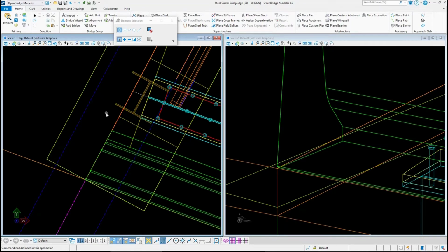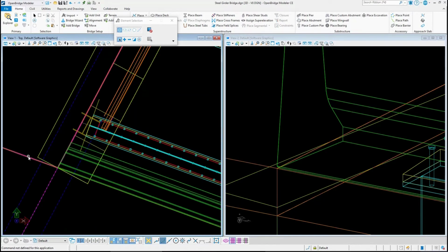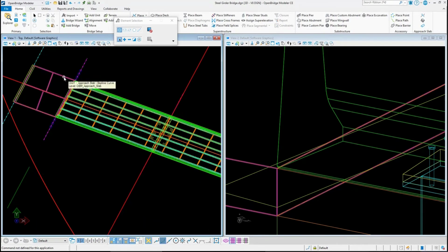Does the rail offset follow the curve geometry? Does the rail or the curve follow the profile when the offset is extended? Yeah, it's following the deck. Actually, it's applying that information to the deck. It's not floating in the air. Or if it's not much, I mean, 10 feet is almost the same. Remember, this approach slab is like another deck, so you can place a barrier just on an approach slab. For example, the approach slab is opening up different from the deck, or it's coming on a curve, and then the bridge is starting on a tangent, so you can place it on top.